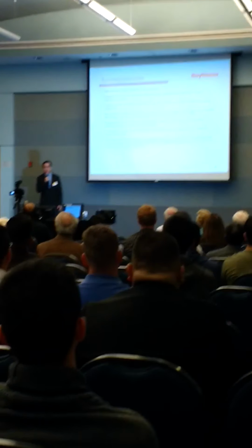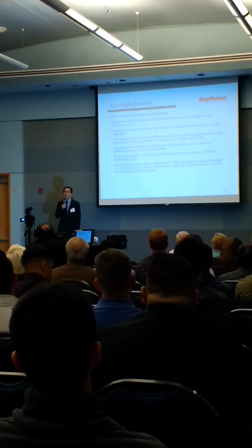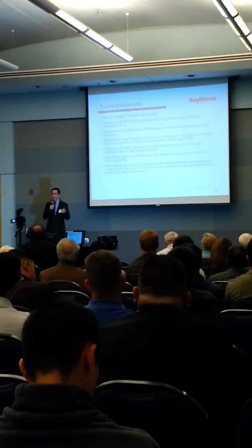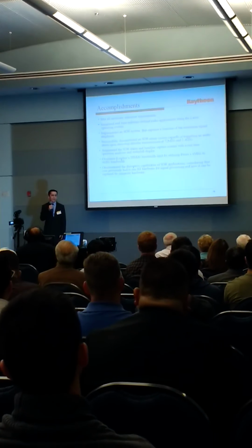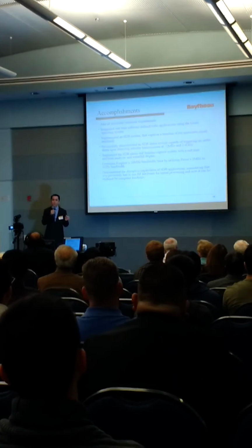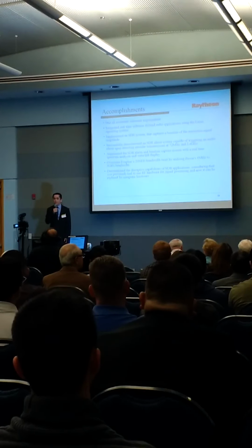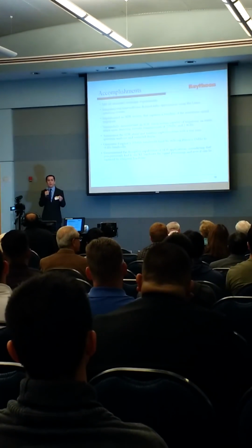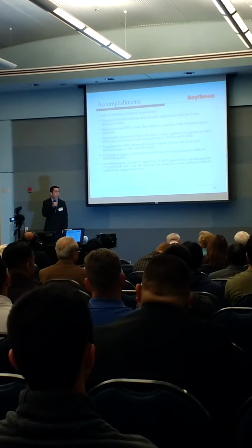Now for our accomplishments. It's important to note that we met all of our requirements. We integrated a software-defined radio application on the Linux operating system, and we also implemented an SDR system capable of capturing a baseline of the maximum signal amplitudes. In addition, we successfully demonstrated that our SDR alarm system is capable of setting off an audible alarm at the frequencies located at 72 megahertz and 2.4 gigahertz.